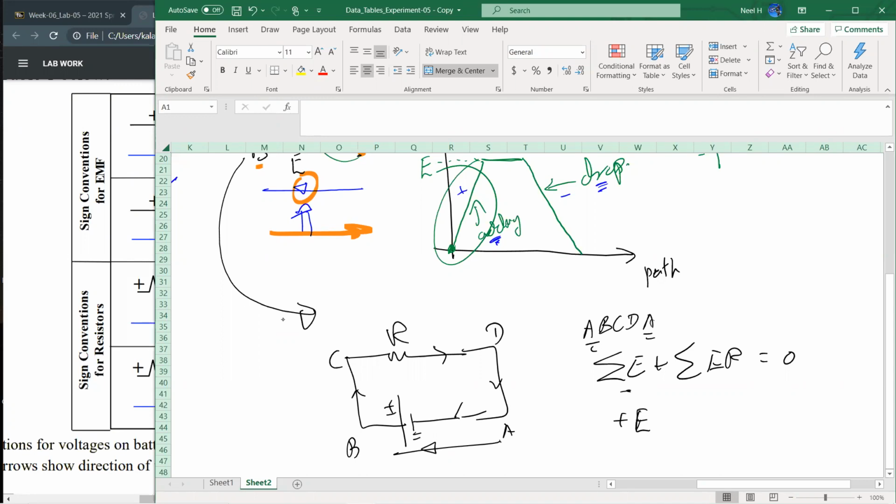And then I have only one resistor, current I. This is the loop direction, C to D. The current direction and the loop direction are the same, so I have to use here minus times IR. Then you can see, since I have one resistor, I end up applying Ohm's law to this resistor, right? The voltage across the resistor should be equal to I and R if you bring this to the other side. So that actually validates the sign rules automatically.